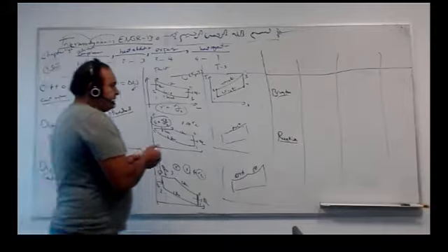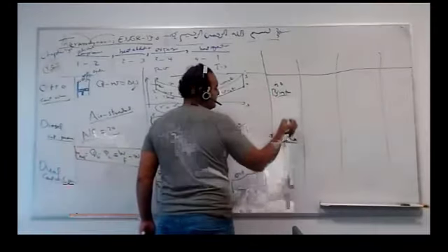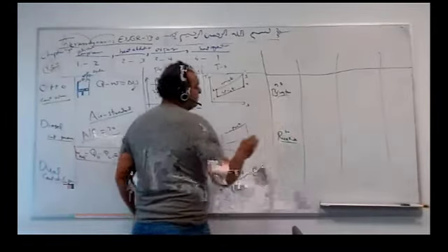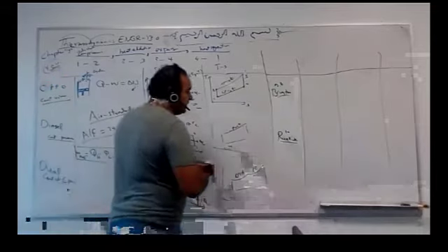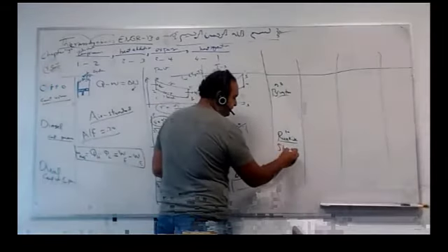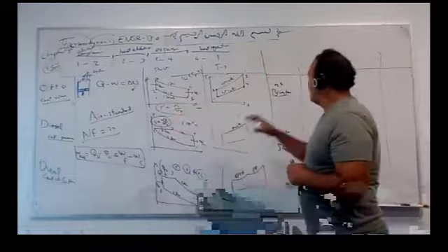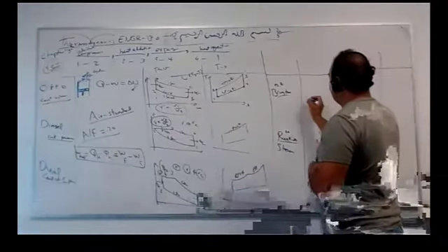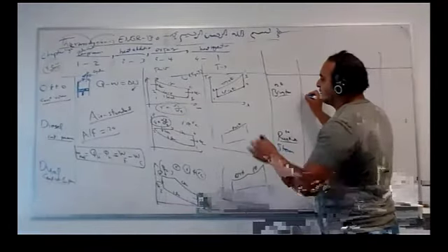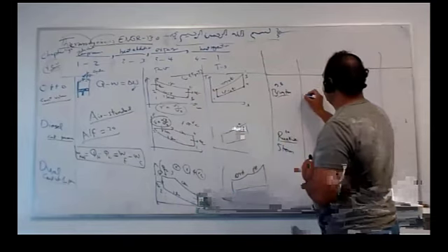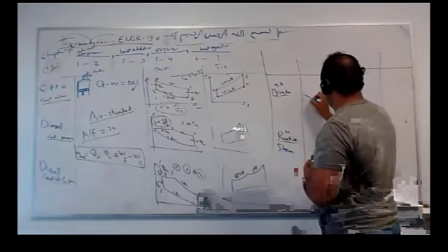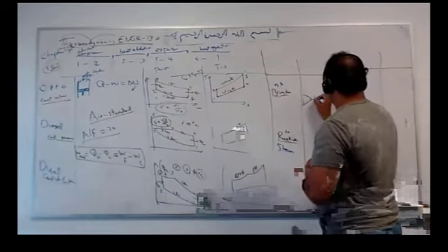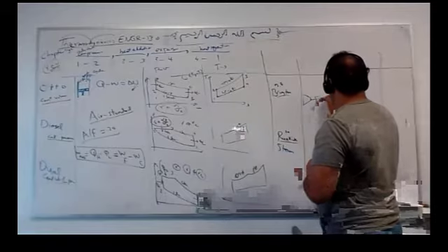Now, let's go to 9.8 and chapter 10, which is Brayton and Rankine. Brayton is still a gas cycle, still an air standard cycle. Rankine is not. Rankine is the only one with steam. We use a steam table. Unlike those, Brayton is like a jet engine. It has different components. It's not like a piston cylinder. It is a compressor, combustion chamber, and you have a turbine.